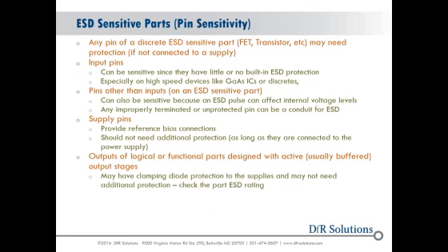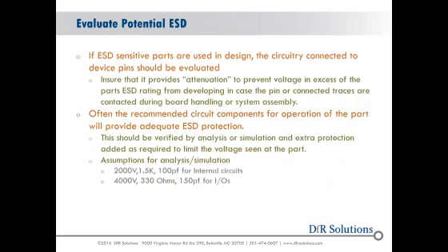Pins other than inputs can also be sensitive because an ESD pulse can affect the internal voltage levels, and any improperly terminated or unprotected pin can be a conduit for ESD. Supply pins provide a reference bias connection. They shouldn't need additional protection as long as they remain connected to the power supply. And outputs of logical or functional parts designed with active, usually buffered output stages, may have a clamping diode protection scheme to the supplies, and may also not need additional protection. You have to check with the ESD rating of the part.